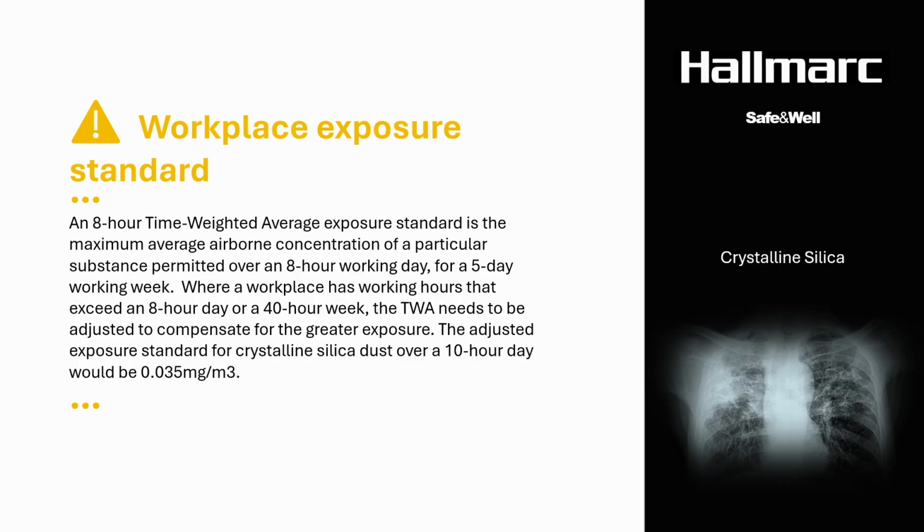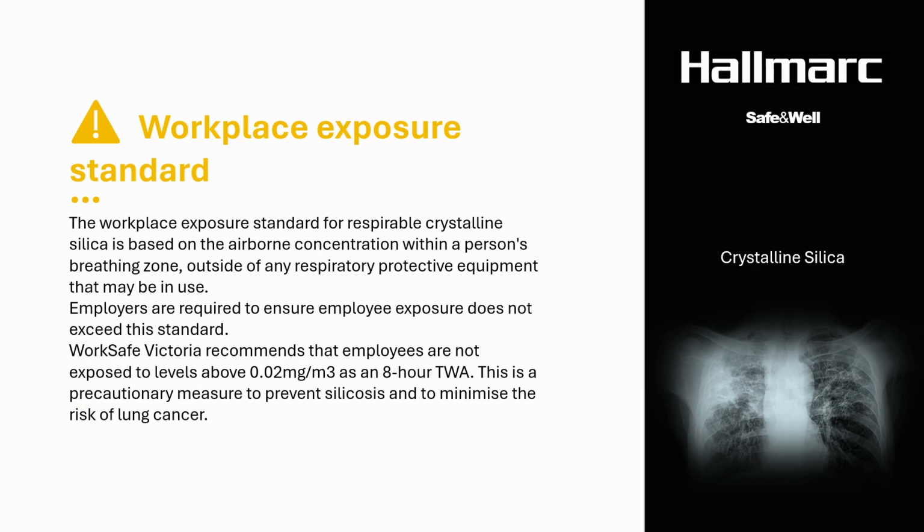Where a workplace has working hours that exceed an 8-hour day or a 40-hour week, the time-weighted average needs to be adjusted to compensate for the greater exposure. The adjusted exposure standard for crystalline silica dust over a 10-hour day would be 0.035 milligrams. The workplace exposure standard for respirable crystalline silica is based on the airborne concentration within a person's breathing zone, outside of any respiratory protective equipment that may be in use.